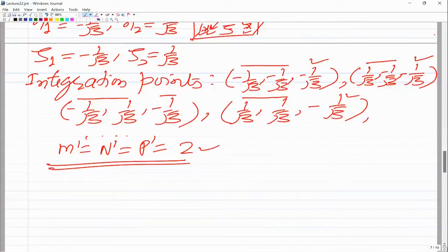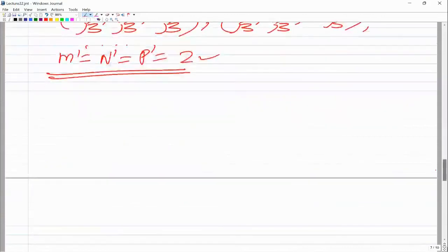But before I move on to the plate bending element, in 2D I have only talked about the 4-noded element, and in 3D the 8-noded element. But we can go for higher degree polynomials. Then we will have 8- and 9-noded elements in 2D, and you can have 20- or 27-noded elements in 3D. That is also possible.